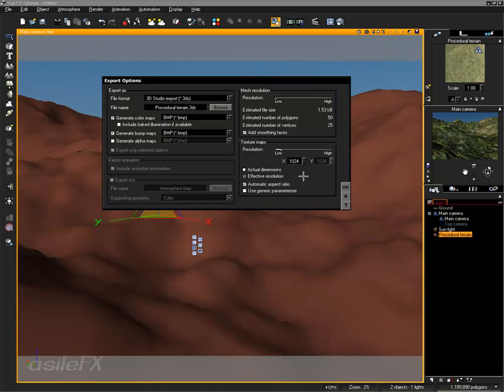One thing to keep in mind is it will render out each of these materials. And the higher the resolution, the longer it's going to take to render. And unfortunately, this export option is a single core process. So you'll basically be exporting and only rendering with the one core. So I'm working on a quad core, and only 25% of my CPU will be rendering this output, which is going to take a lot longer to bring it out.